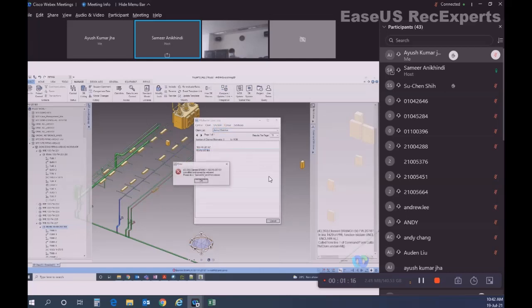It is saying that you have made changes. You must save work first and then release the element. So without saving work, you cannot unclaim. Now it is claimed, saved. You can unclaim all. See, now the list is empty. Manage claim list is empty. That means you have no element claims in the current hierarchy, and the hierarchy also becomes back to normal font. Earlier it was bold font. Now it becomes the normal font.